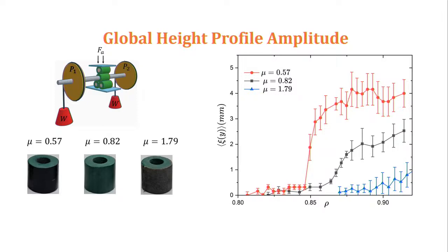If you are below a particular critical density, then it's flat, there is no out-of-plane buckling, and then it starts to buckle. If you change your friction factor, things don't buckle. You can go to very high densities, at least initially, but with high friction there's hardly any out-of-plane buckling. So out-of-plane buckling is being suppressed by adding friction to my system.